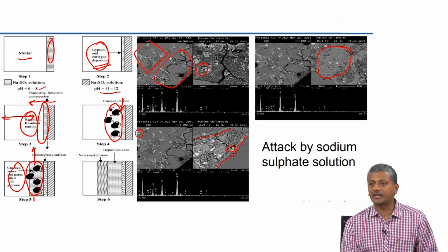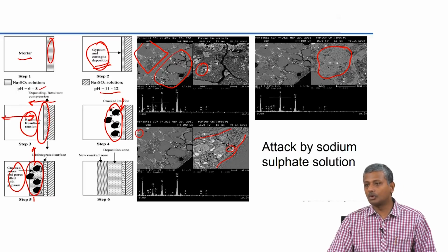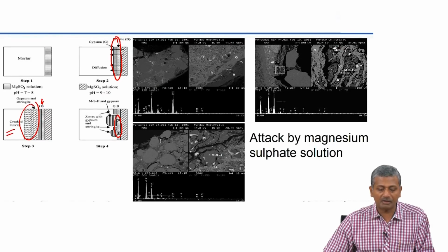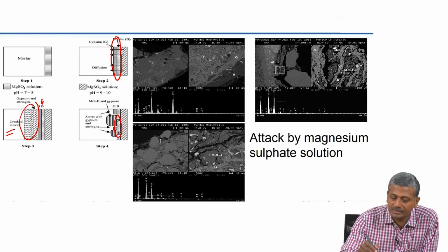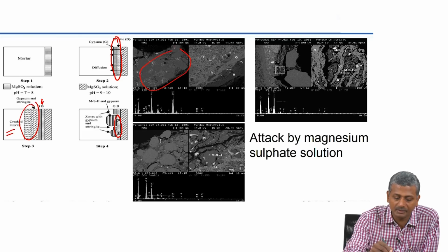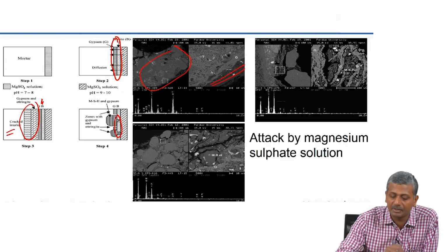So, based on microstructural evidence and the way that the length change happened in the system, I worked out this mechanism which would explain the role of different kinds of chemical and mineral additives in the system. In magnesium sulfate, you can see very clearly at the early stage, after about 12 weeks of attack, you do not really see that much damage here in the surface zone, because you have a very stable layer of brucite, and just underneath that you have a layer of gypsum forming inside.